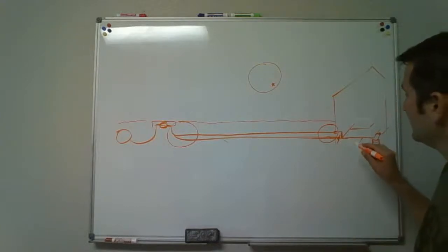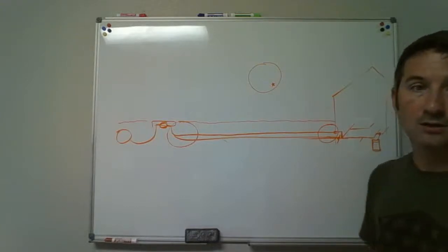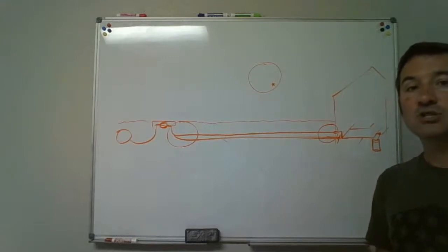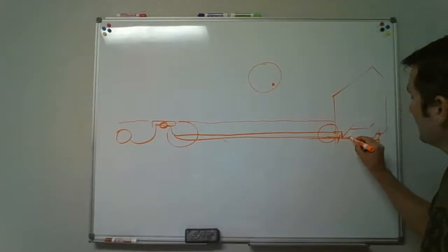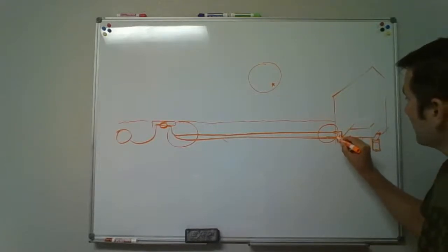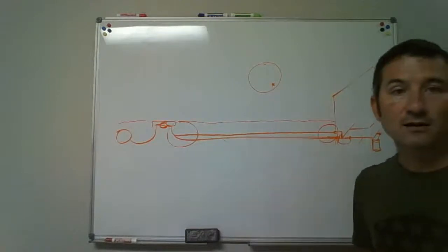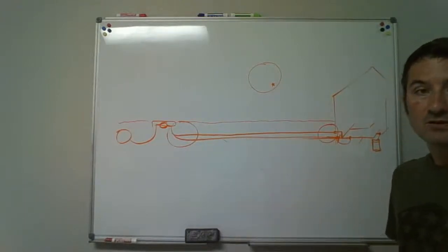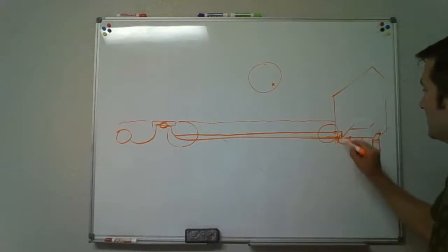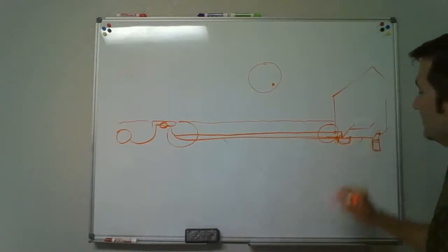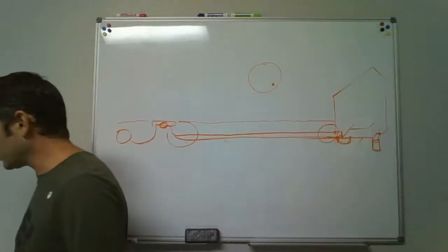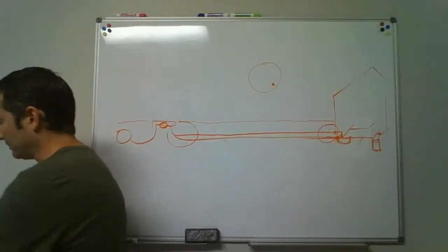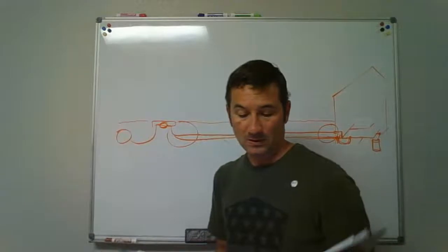So what I did is we took a jumper wire and we jumped it from his existing copper pipe in here and used a copper jumper wire and attached it to the copper line that ran out under the ground that we left in the ground so that it could keep. So we needed that little jumper wire to make this legal, according to 601.3 in your code. All right.